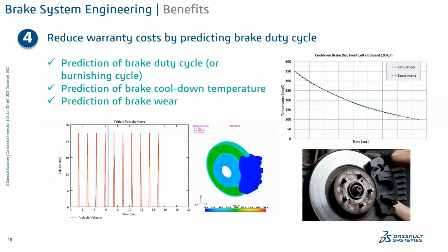A vehicle may accelerate and decelerate through the brake a number of times in its lifetime, for different speeds, different torques, etc. This can be captured through the brake duty cycle, and this can be used to improve the braking system. Also the brake cool down temperature and brake wear can be predicted through the simulations.